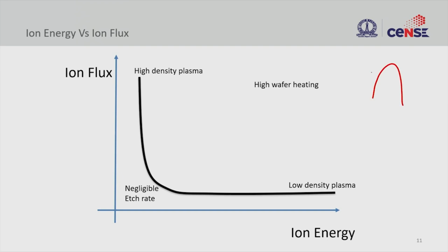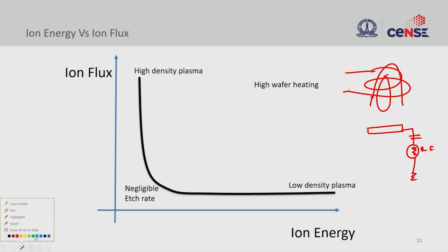There is a dome, and this dome creates the plasma, and my wafer is kept below this dome, and here you put it through an RF. So you have an RF going through, of course, a blocking capacitor, and here you will also have an RF current feed. When you generate it, plasma is generated here. The plasma is generated here.